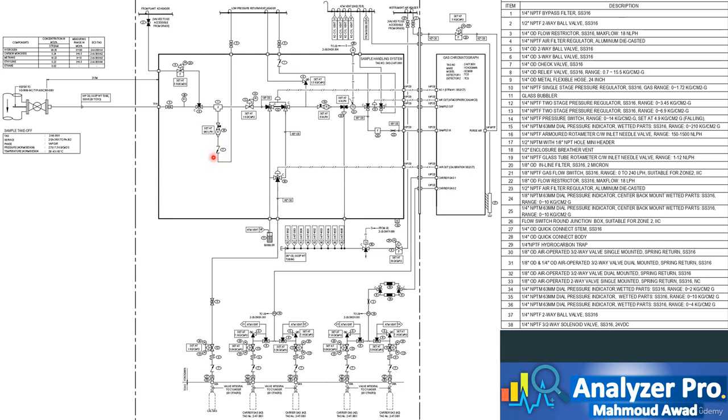The low pressure return header is a header that collects all the streams that will be returned to the process and is directed to a point in the plant that has a stable and low pressure to provide stability to the complete header. The second direction is the analyzer direction. The sample exits the bypass filter to a pressure-reducing regulator. It decreases the pressure of the process, that is 2.78 bars, to 1 bar, and maintains this pressure stable if the process pressure increases or decreases.